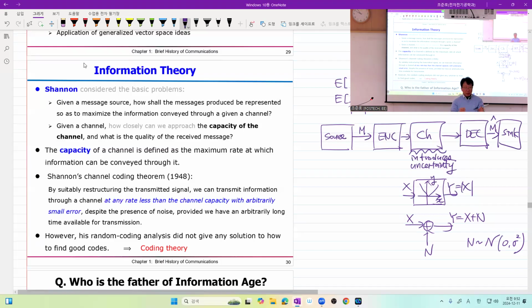And you have cables. And inside, we have electrons that carry the voltage or current flowing in the antenna and circuit. Due to thermal noise, because we are living at temperatures higher than 0 Kelvin, everything jitters, even electrons. And even though it's a free electron flowing in the metal, free does not mean it is not affected by the grid of atoms. So when it moves from one atom's orbit to another atom's orbit, what happens? There is some resistance. And sometimes this electron goes backwards and forwards, even though there is no voltage applied.